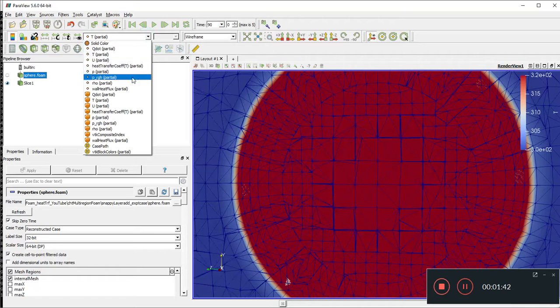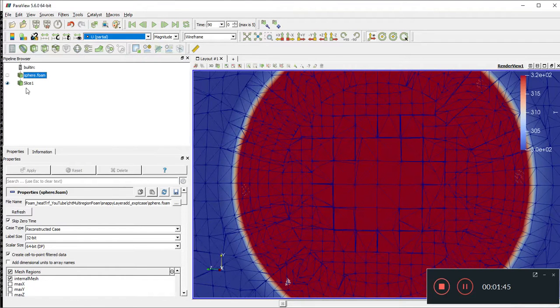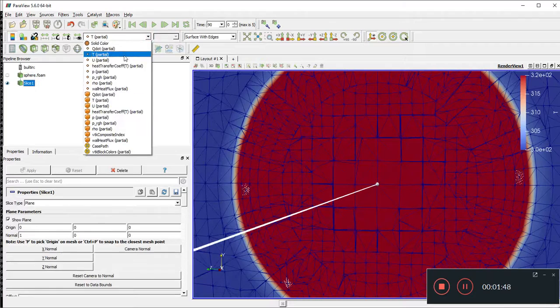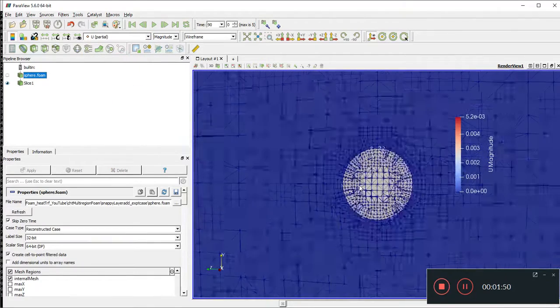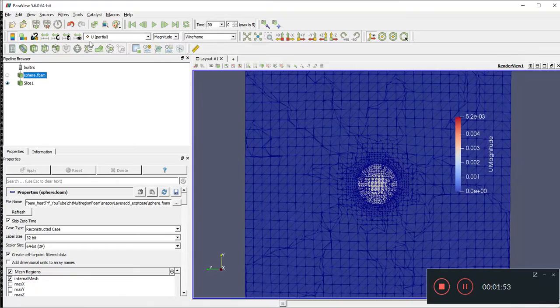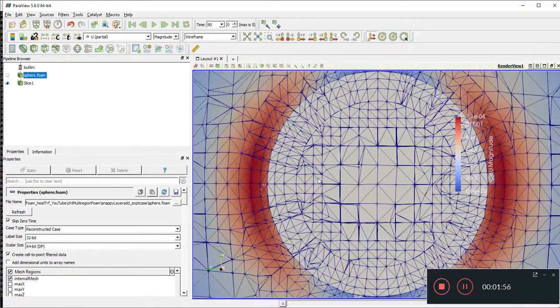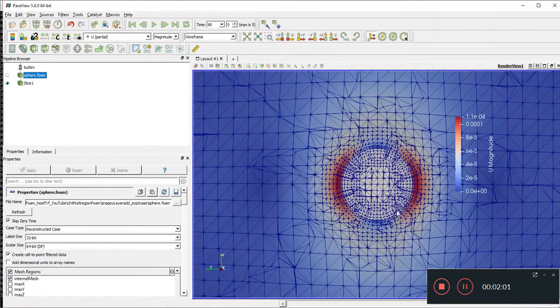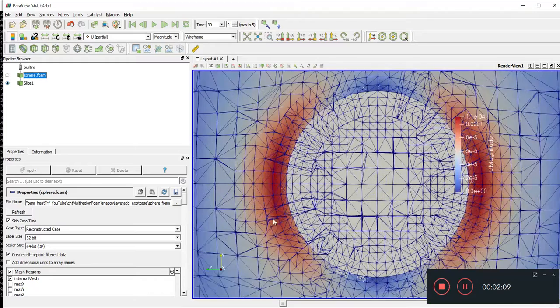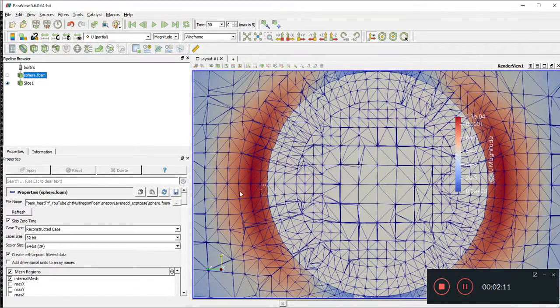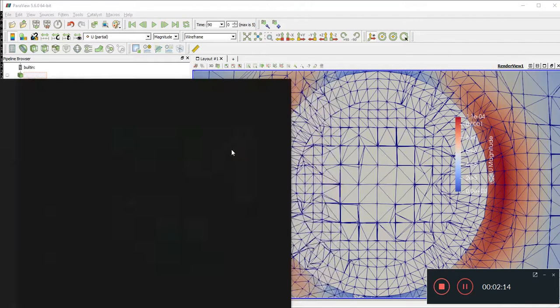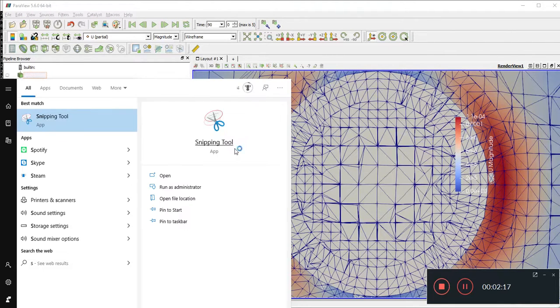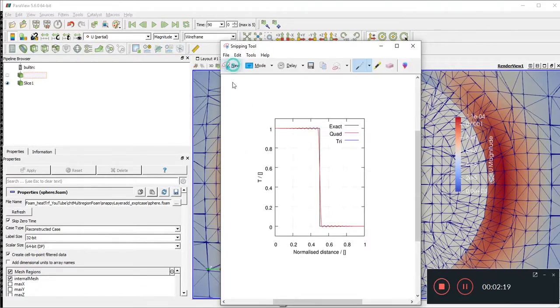mesh, and if we use the velocity profile, we will be able to see the magnitude of velocity, and we'll be able to see the solid region and the fluid region. So apparently there's not much convection going on. And the possible reason why that might be is that the meshes, especially in this region I'm circling, the meshes in that region